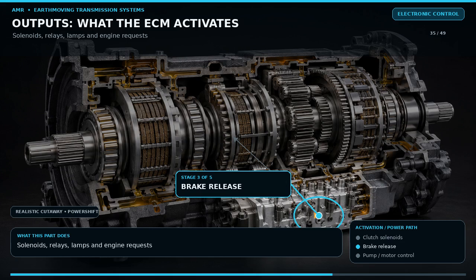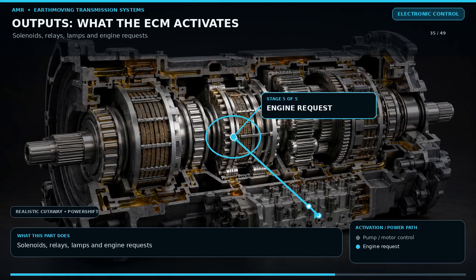It can also request engine torque reduction, desired engine speed, or fan speed over the data link. Warning lamps and display messages are outputs too. Use a schematic to identify whether the controller supplies voltage, provides a ground, or sends a pulse width modulated current. Never apply battery voltage directly to an unknown proportional solenoid. Incorrect current can damage it or cause sudden machine movement.